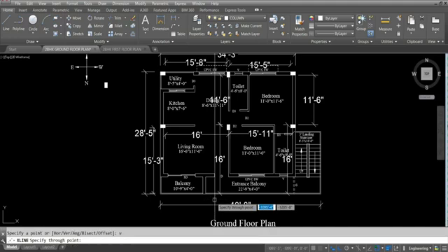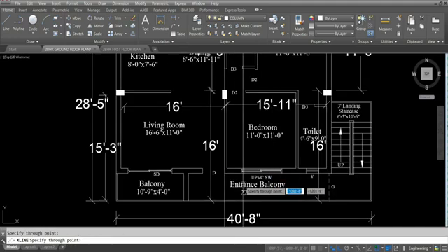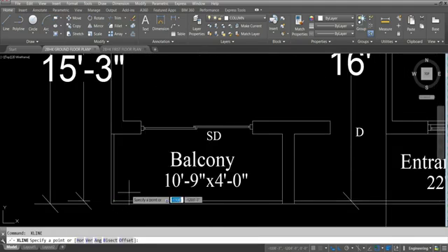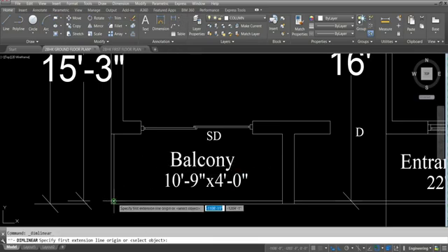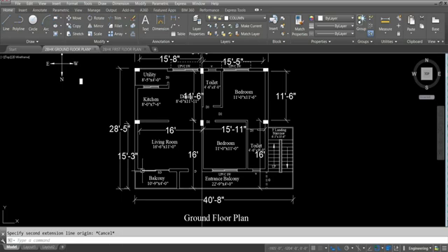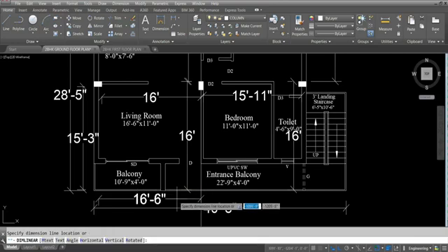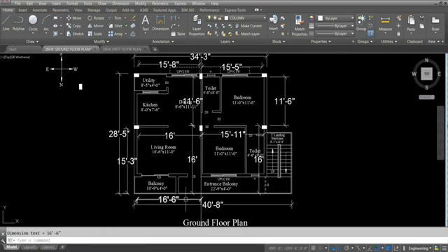See, I will take a vertical construction line. I'll check the dimension again. Here to, sorry, this point. End to end we have to take, no? Here to here is 16 feet 6 inch. Okay. So 16 feet 6 inch is obviously greater than 15 feet 3 inch. So more load is coming from which side? This side, 16 feet 6 inch, to this column. More load is coming. So the shorter side of the column should be oriented towards this side, the 16 feet 6 inch side.